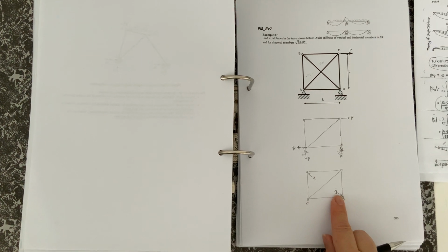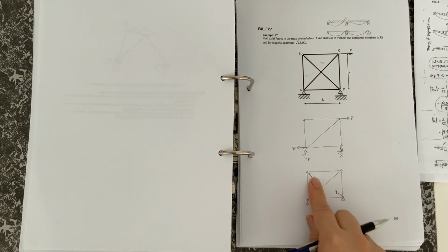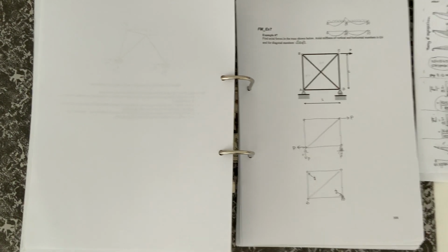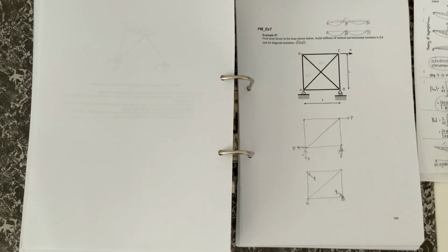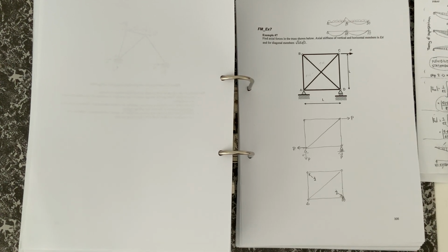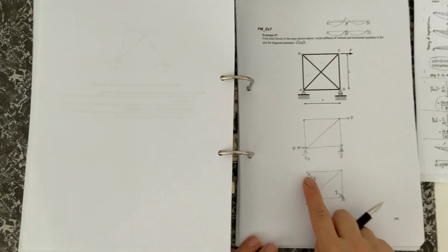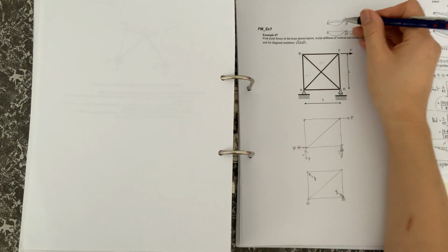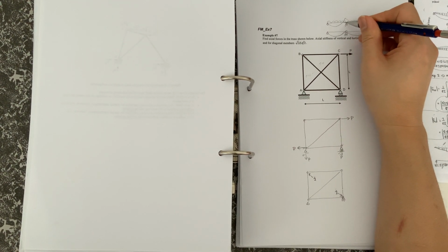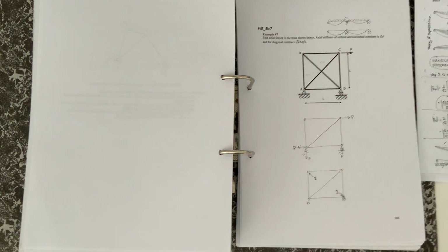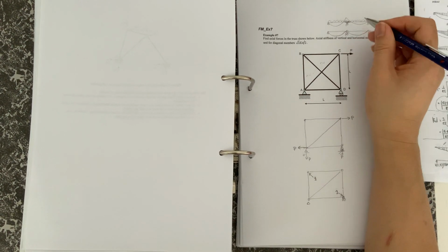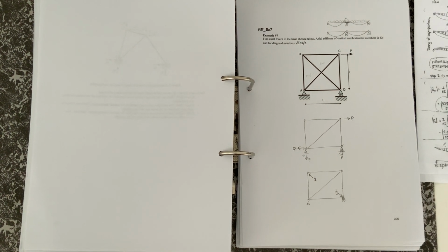And in this case here, we're adding back the effect of the diagonal member by applying 1 here, which we can scale upwards. So last time we used the factor x to scale it upwards, such that, before, the condition was we wanted to make sure that at the end it didn't deviate off the 180 degrees, or there wasn't a kink in terms of the deflected shape.